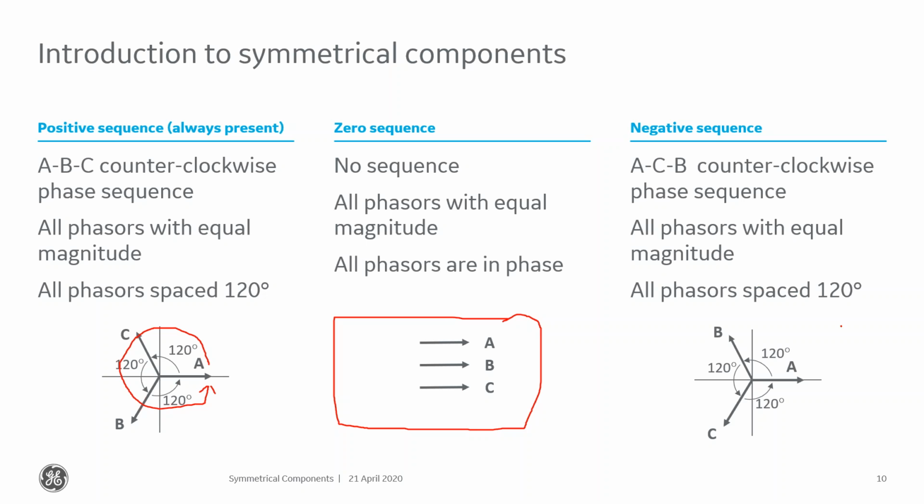And then the negative sequence network here has a reverse phase rotation. So for it, what I expect to see is, if my eyeball's standing right here, so this is my eye, let's see how good of a drawer I am. Oh, I've got eyelashes at the top, not at the bottom. I guess I do have them at the bottom too. But if my eye's standing right there looking and this thing is rotating counterclockwise, I expect the sequence to pass my eyeball to be ACB. So it has ACB rotation.